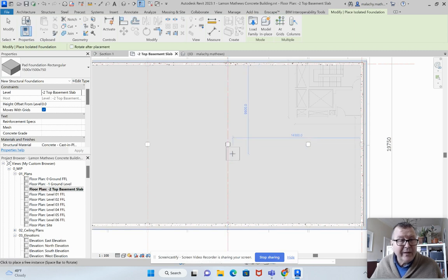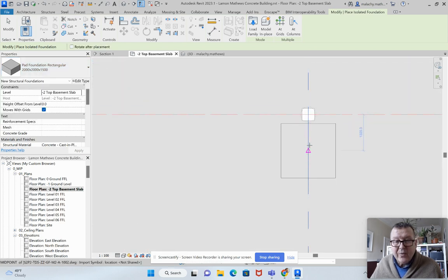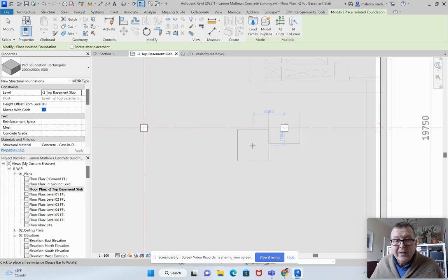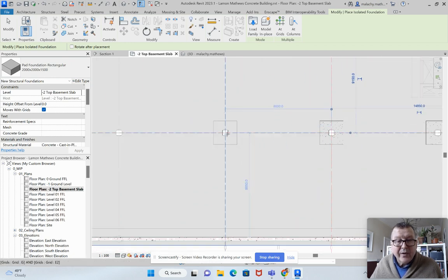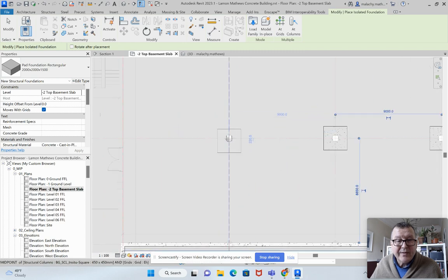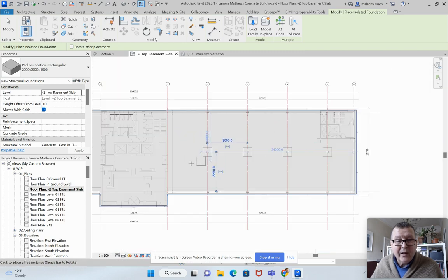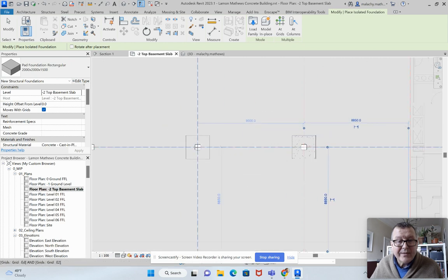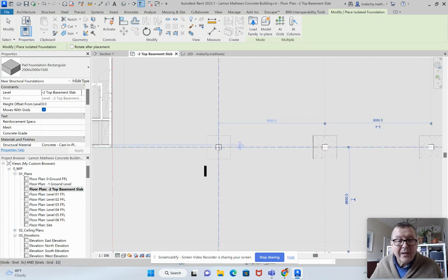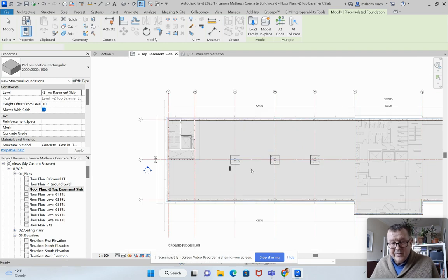Now, so it comes in, right? That's not the one I wanted. It was this one. Comes in attached to my cursor. And what I'll do, it'll go and find a column. So you can go and find a column which is on the intersection of our grids, like so. And wherever there's a column, you pop that in place. And it's going to ask me what level does this come in at. So we hit escape, escape.